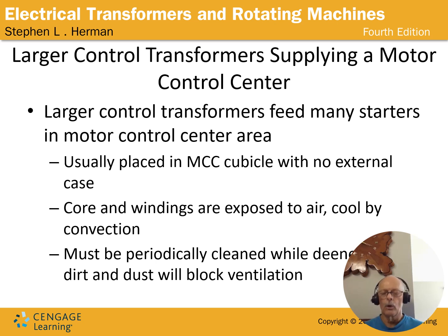Always remember in heat transfer, heat always moves from a warmer device to a colder device. Cold does not flow. Cold draws the heat away. And as the heat is distributed through an object, the temperature begins to decrease and fall. So when this convection happens, the cool air is drawing heat off of the transformer and expanding.